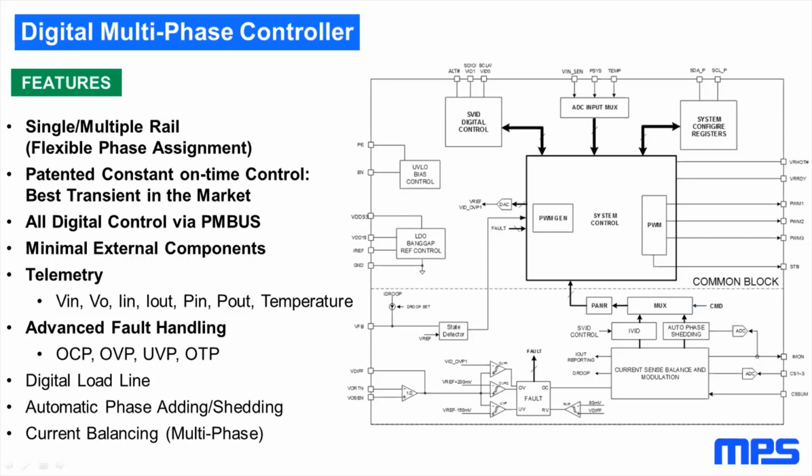For example, if you have 3 power stages and the middle one becomes too hot, you can distribute the current difference so that the outside power stages get more current and then have the same temperature as the middle one. But this happens quite seldom.